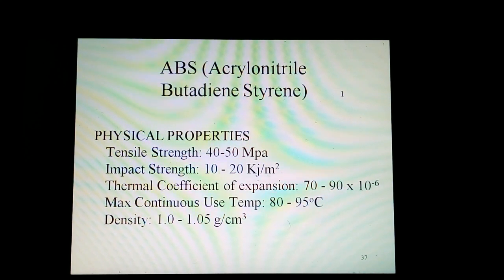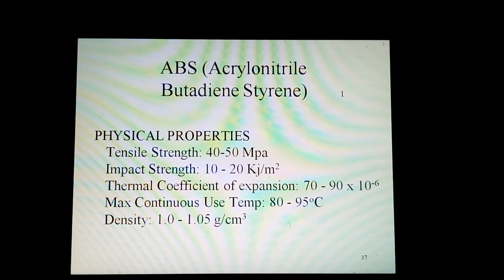Physical properties are: tensile strength is in the range of 40 to 50 megapascals. Notched impact strength is in the range of 10 to 20 kilojoules per square meter. Thermal coefficient of expansion is in the range of 70 to 90 x 10^-6. Maximum continuous use temperature is in the range of 80 to 95 degrees centigrade. Density is in the range of 1.0 to 1.05 grams per cubic centimeter.